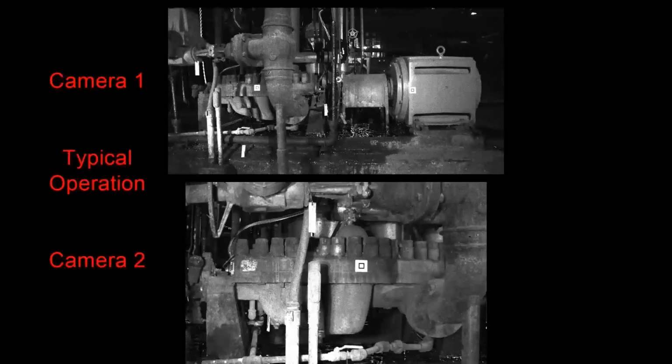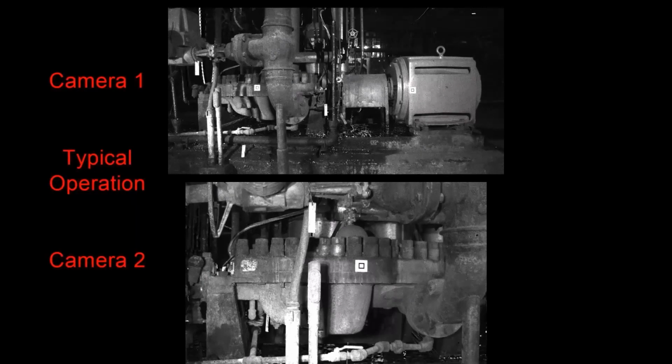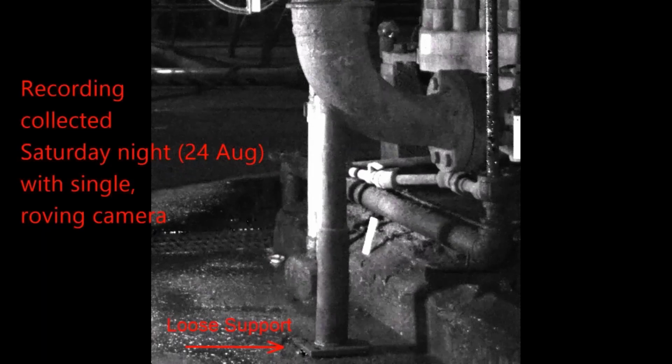And then it was also run overnight and actually triggered off of these. So these are 2 camera views, triggered off these events where they captured a support that was loose because it went through an elevated level of vibration. And so we'll see that here in a second, where this support gets loose. So again, the point of this is not necessarily to focus on the motion amplification.